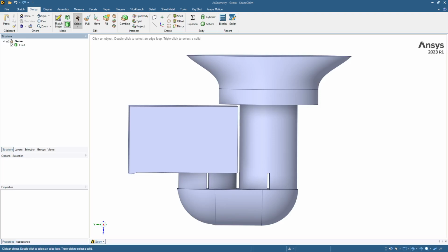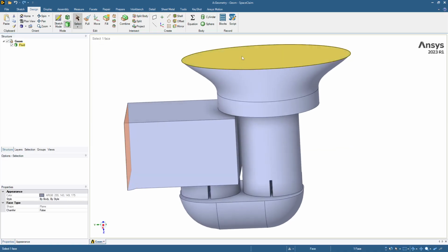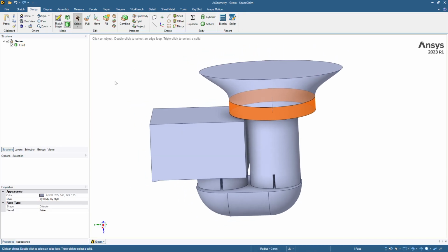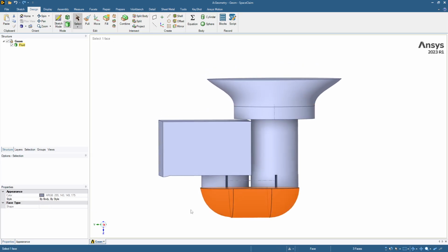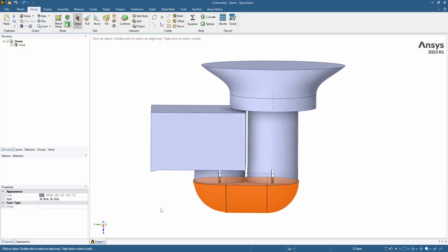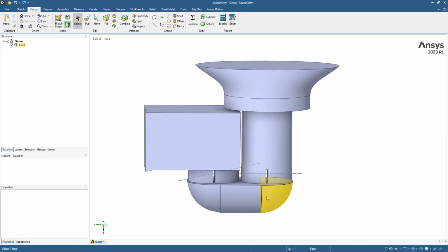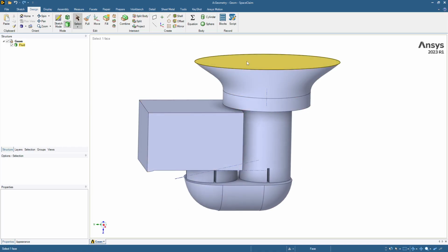I'm learning CFD and Fluent, and this is an airflow fluid volume for a device that has an inlet here, an outlet there, and this is another inlet for bypass airflow, so it doesn't all go through this bottom section called a blister. I'm interested in the pressure drop across the blister, as well as the velocity in there, and then the relative contribution of mass flow out there from the bypass inlet or the main inlet.